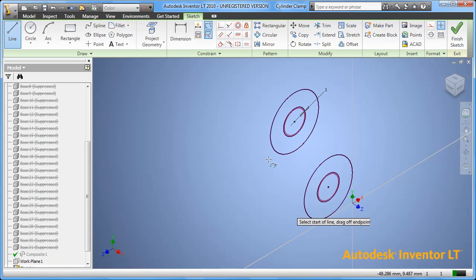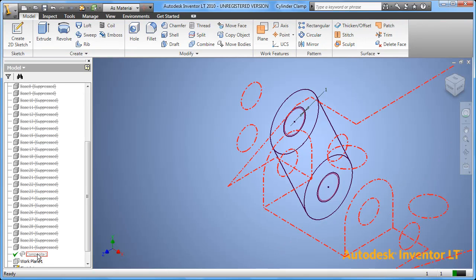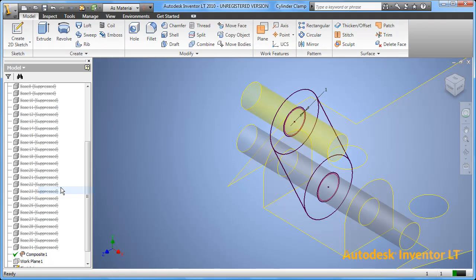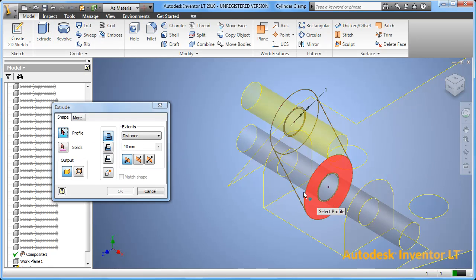Based upon how the geometry is created, the number of constraints that need to be added at a later time can be minimized. Here, I'm taking care by creating my line so as to establish tangency at the time of creation. With my 2D sketch now defined, I can exit from that environment, turn on the visibility of my extracted surfaces, and create some features based upon them.